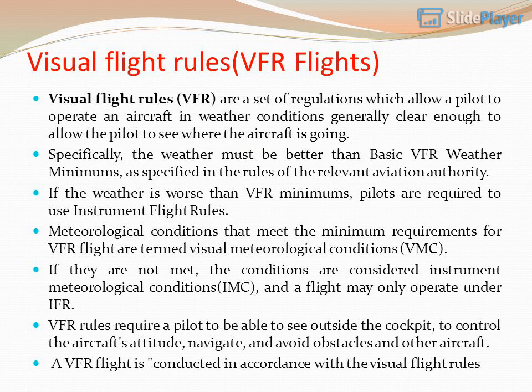Visual Flight Rules, VFR, flights. Visual Flight Rules, VFR, are a set of regulations which allow a pilot to operate an aircraft in weather conditions generally clear enough to allow the pilot to see where the aircraft is going. Specifically, the weather must be better than basic VFR weather minimums, as specified in the rules of the relevant aviation authority. If the weather is worse than VFR minimums, pilots are required to use instrument flight rules.